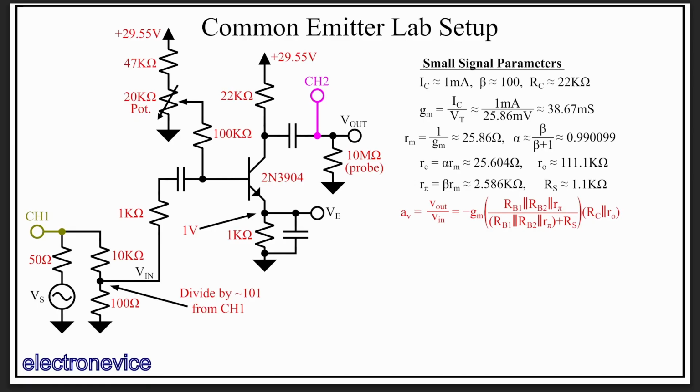This is very simple to remedy. All we're doing here is taking the Thevenin equivalent impedance of our biasing network and putting it in parallel with Rpi as the total impedance from the base to ground, which acts as the lower resistor of a resistive divider, with the upper resistor being Rs.